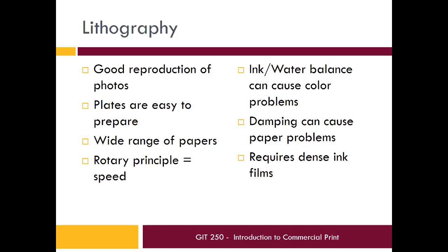Fiddling around to get that set up just right is difficult and leads to an increased make-ready time. So let's say that you're going to print 500 pages of some document or a flyer, then that's going to be difficult because it's going to take you a significant amount of sheets running through that press just to get everything up to speed, get the ink-water balance right, get the ink spread out evenly and reproducing correctly. You can also end up with problems because the paper gets too wet or because the ink is too dense, and so the pages will start to stick together and you end up with a really expensive brick of paper at the end.